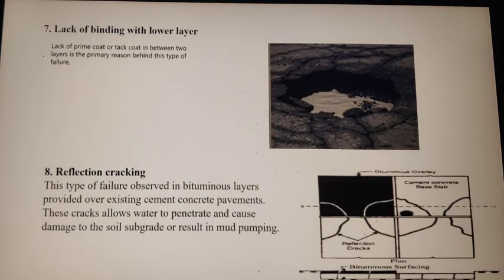Next is the lack of binding with the lower layers. This type of hole will develop. The lack of prime coat or tack coat in between the two layers is the primary reason for this type of failure. So we have to provide the prime coat or tack coat.